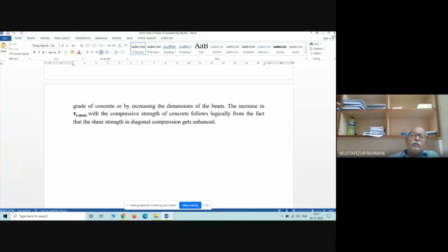Now for stirrups, for our normal construction, say for building, it has some specification also. It may range from 5 millimeter to 12 millimeter diameter. Okay, it has some specification in IS 456. If you have already downloaded it, you can go through it. That will be useful in your code, in your examination. So for that, we'll be able to find out the spacing.